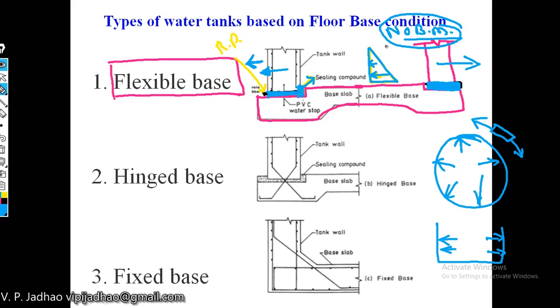So if we don't want any bending moment to be developed in your water tank wall, then we will be using this type of water tank with flexible base. These are very rarely constructed, and I haven't seen any water tank constructed using this particular technique of flexible base.